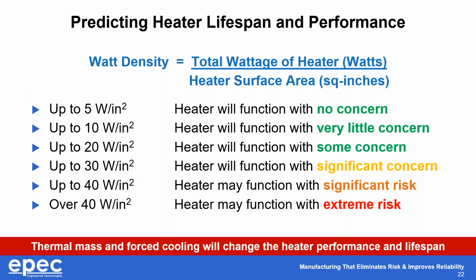As a rule of thumb, heaters with 10 watts per square inch and below are typically no concern whatsoever. As you increase the watt density, which is driving the heater harder and harder, you develop hot spots. You potentially can see some blistering or bubbling of the polyimide because of localized non-uniform heat generation.